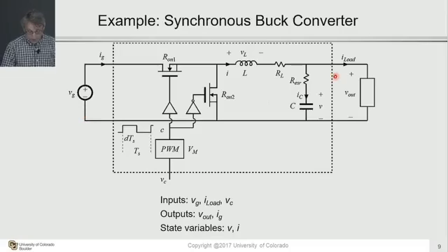The inputs in this case would be the input voltage, the load current, and the control voltage that really sets the value of the duty cycle D. The outputs would be the output voltage, but also we treat the input current as a "quote mark" output, and you will see that has particular importance when we get to the point of designing an input filter. Then the responses from, for example, duty cycle to input current are going to be particularly important in studying how the input filter is going to respond to that type of perturbation.